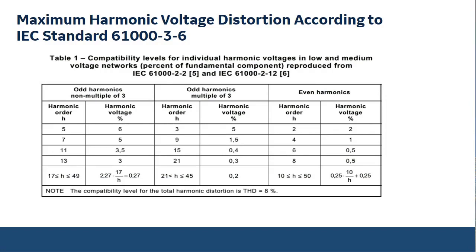And if it's a greenfield installation, we really can't go there and make the measurements either. So then we come to this. We get from the standards. Here what I'm showing is an IEC standard. From the standards, we can say the maximum compatibility level of harmonics that can be in the network. So this is something that all components in the network must withstand.